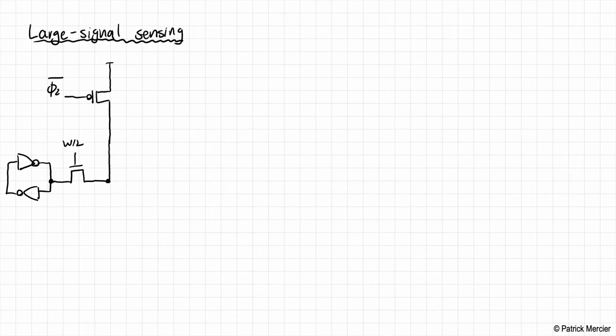I'm just drawing basically half of the SRAM cell. Then we go through our entire bit line, and then eventually we get our output. In this particular case, this would be looking at bit bar in the example that I showed earlier. So bit bar does discharge, and eventually it'll discharge all the way to 0, if the leakages and so on work themselves out.